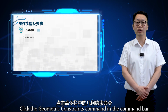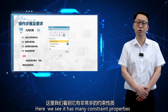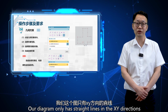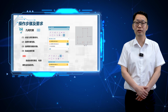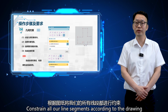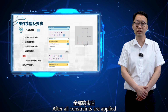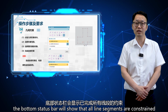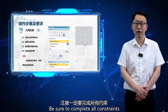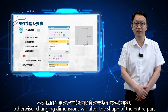Click the Geometric Constraints command in the command bar and select the constraint properties. Here, we see it has many constraint properties. Our diagram only has straight lines in the XY directions, so we only need to choose horizontal and vertical constraints. Constrain all our line segments according to the drawing. After all constraints are applied, the bottom status bar will show that all line segments are constrained. Be sure to complete all constraints, otherwise, changing dimensions will alter the shape of the entire part.